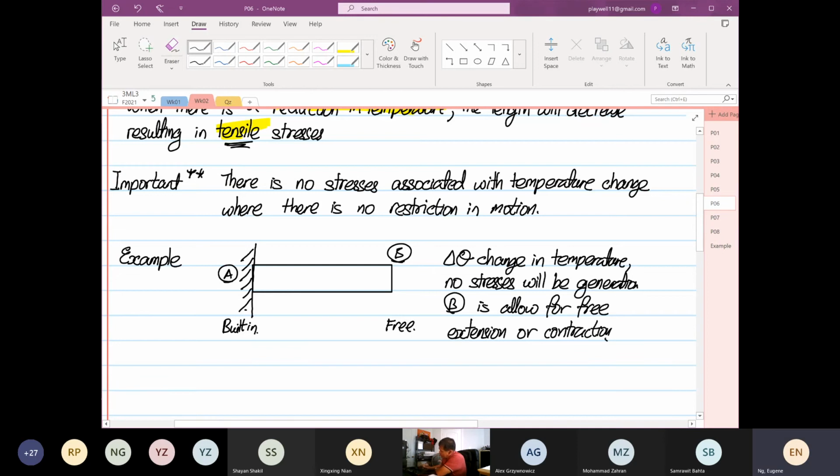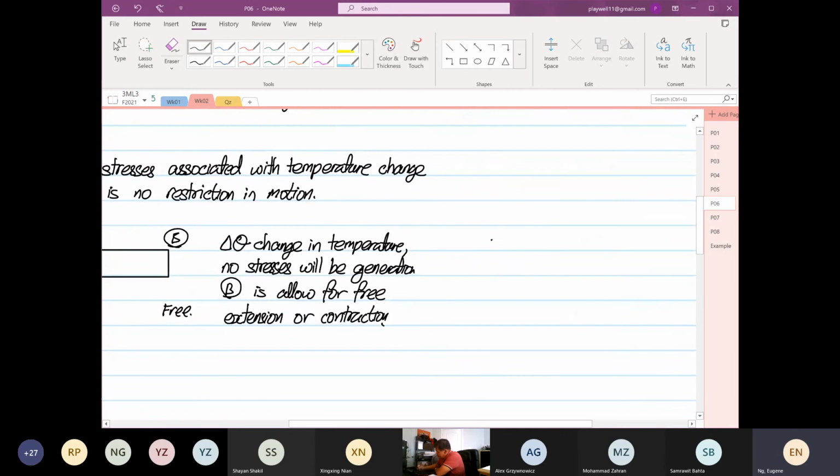Right? So that is why in Canada, especially, when we design a bridge, one end is pinned, the other side is on a roller. Why? If I have a transformation over here, and this is my X and Y, and this is our rotation in Z. When it's pinned, X motion is equal to 0, Y motion is also equal to 0.